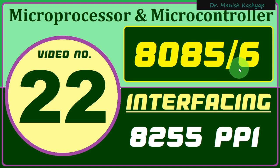We do not want it to check the status of peripherals, whether it is ready for transfer, whether it is not ready for transfer, so on and so forth. So this task has been given to this special IC, which is called as 8255 programmable peripheral interface. And since it is programmable, it will reduce the burden of this microprocessor, either 8085 or 8086, right? So that's what we are going to study today in this particular lecture.